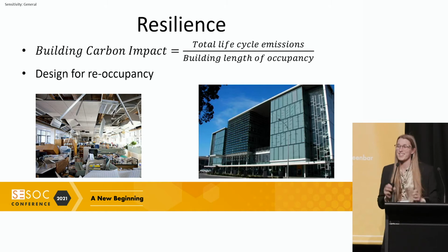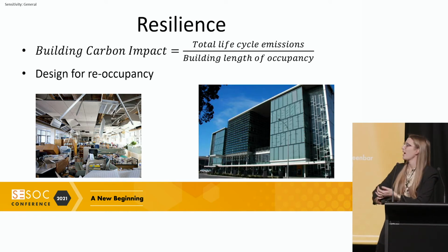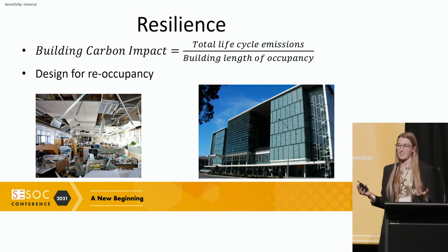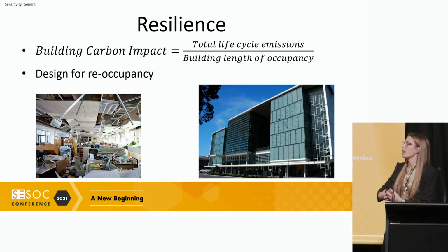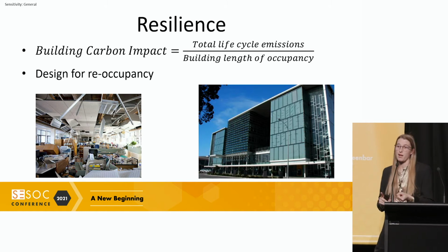Resilience has been a bit done to death, so I'll just gloss over it with that sustainability lens. From a carbon perspective, which is only one aspect of sustainability, obviously the longer a building is in existence, the lower its annual effective carbon impact will be. So yeah, we do want to be designing our buildings to be up there a long time, if at all possible. Designing for reoccupancy is really important, so those earthquakes that come along that are perhaps less than ULS, and I know it's been talked about a lot already this morning, provide a high level of protection to those non-structural items so that you don't need to throw things out and re-put them in.